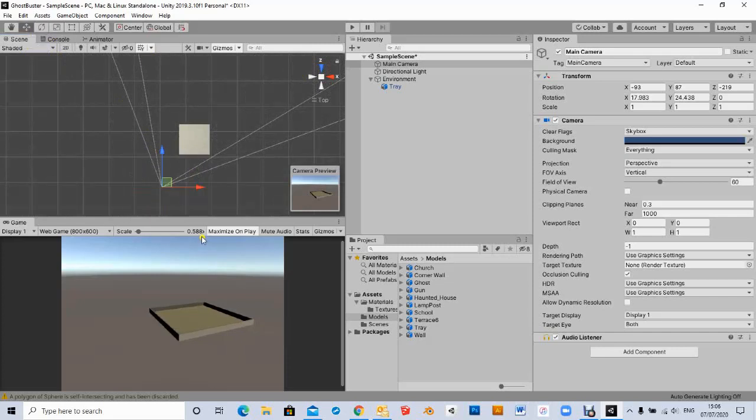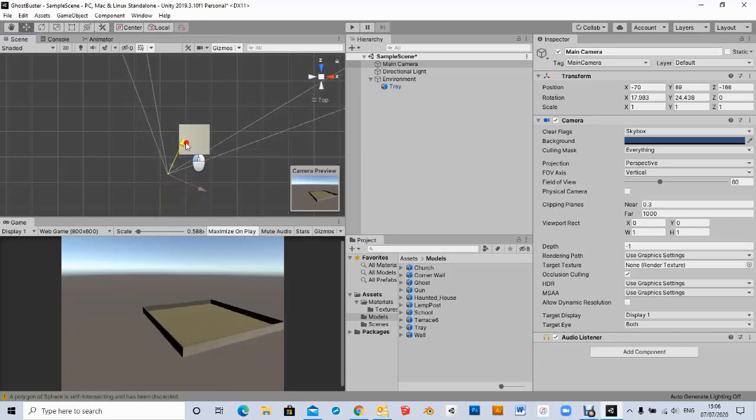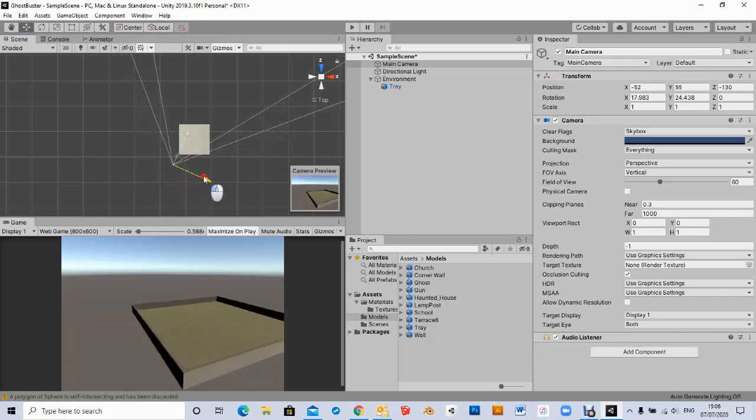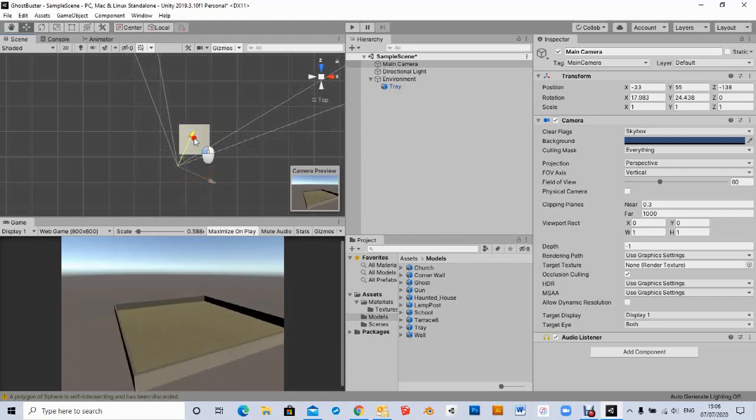Now I'm going to show you a bit about these axes. Every object has got its position in space, and these are the global axes. But every object knows its rotation and its position because we've put it in the transform. So I can look at the local ones here. If I just click on there, you can see that it knows this is its forward motion. So I can move it forwards or sideways. It knows all about that. Then click back on here to go into the global again.